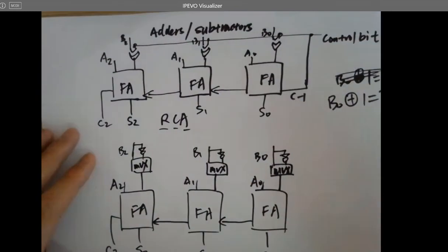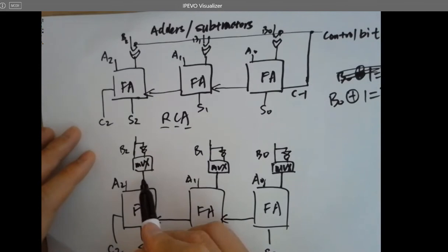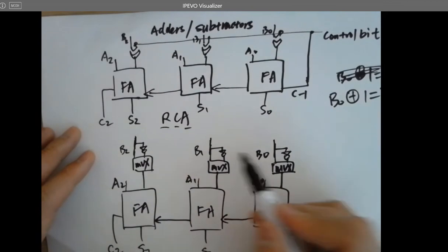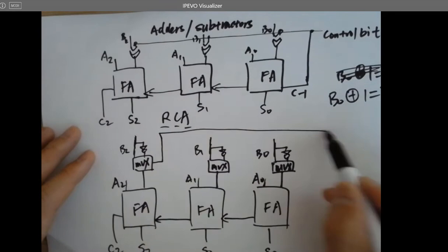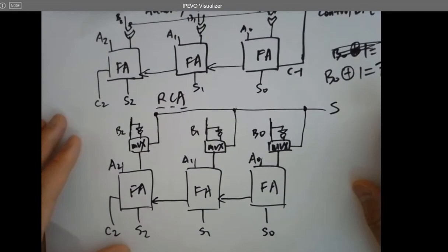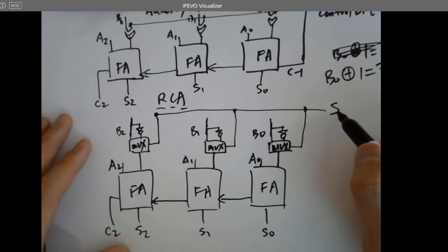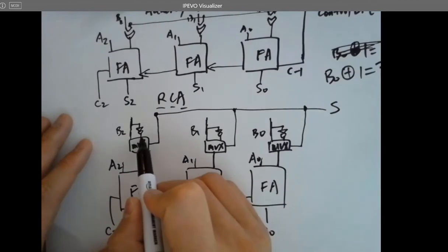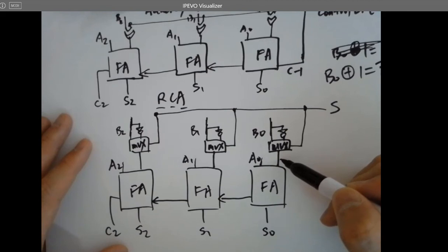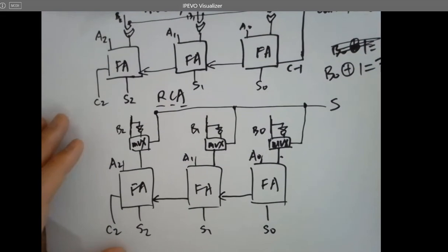A mux selects either input and transfers it to the output, right? Depends on the control bit. So here is B, this signal is B, and that's B naught. All these ones are B naughts. And this is the control bit, which is a selection bit. Let's put S here. There are two inputs being fed into the muxes. So if I give a 1, then I can select all the B naughts as the output of the mux. If I give a 0 to S, it's going to pick up all the B's. That's a function of the mux, right?